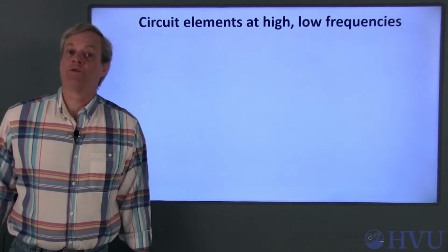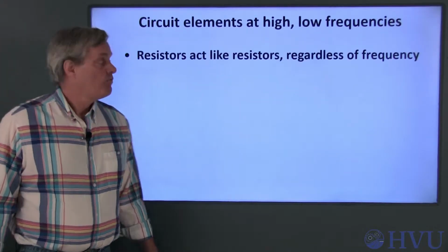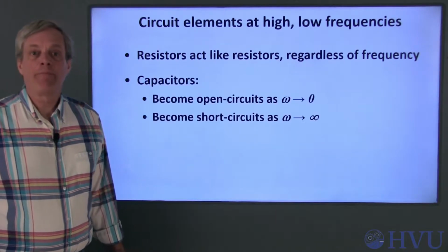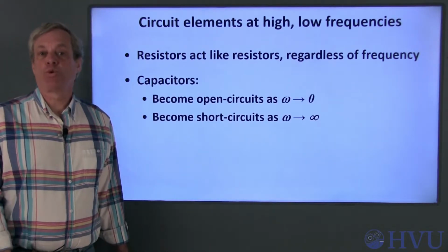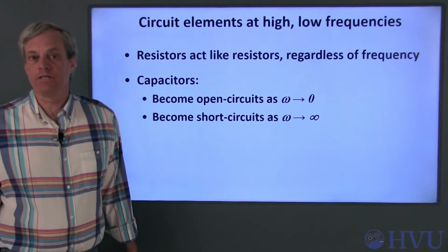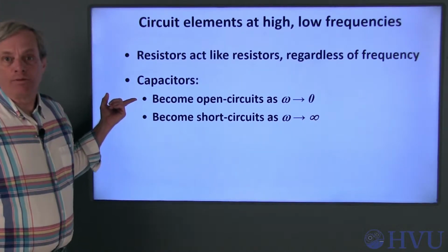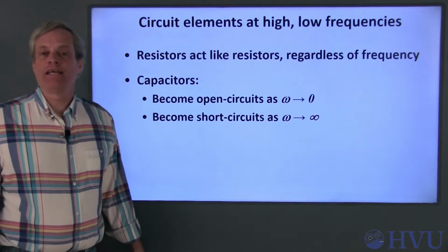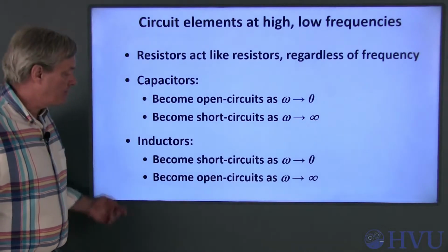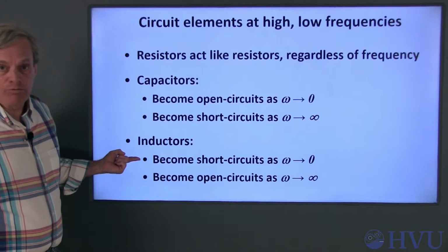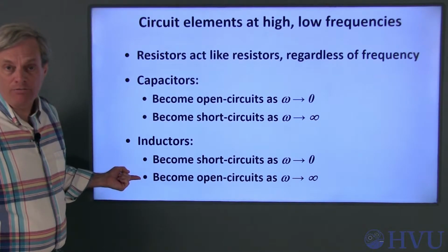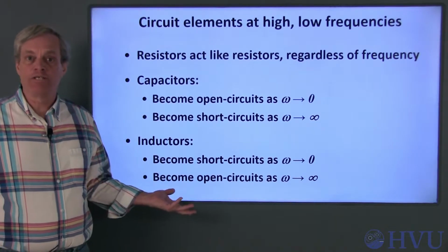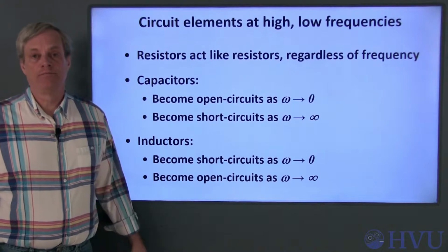This is important, so let's summarize these results. Resistors always look like resistors, regardless of the frequency. Capacitors, however, can be modeled more simply at low and high frequencies. At low frequencies, you can replace a capacitor with an open circuit, and at high frequencies, it can be modeled as a short circuit. Inductors can be modeled as short circuits at low frequencies and open circuits at high frequencies. Next, we'll do an example to see how this helps us check our frequency domain circuit analysis results.